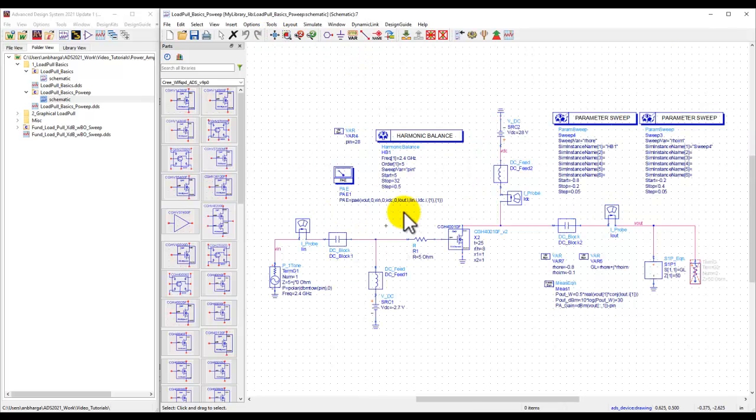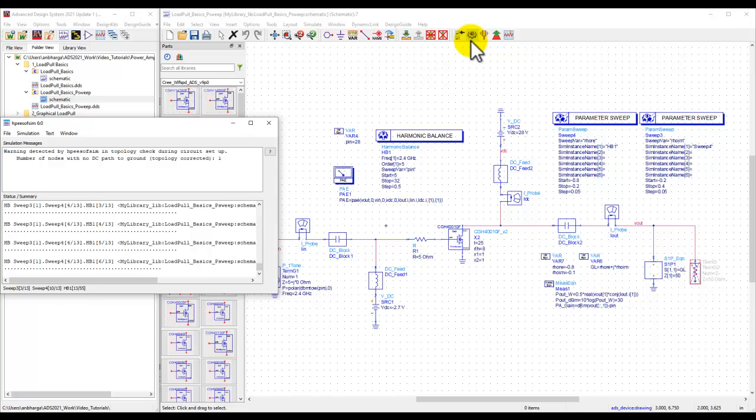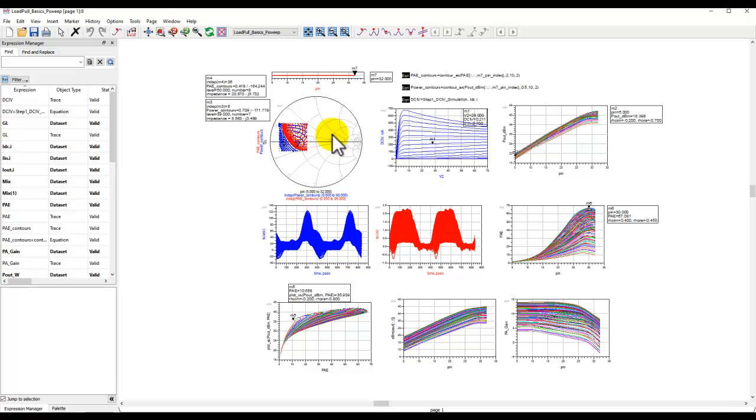Now when we do that, basically the output power which we are going to calculate at this node will have a three variable array: two variables as we had already seen before, and one more extra variable which will get added due to this Pin. So let's perform a sweep and let's look at the data at the output. Now whenever we are doing this kind of sweep, we can have as many sweep variables as you want, and you can come up with multi-dimensional data as you need.